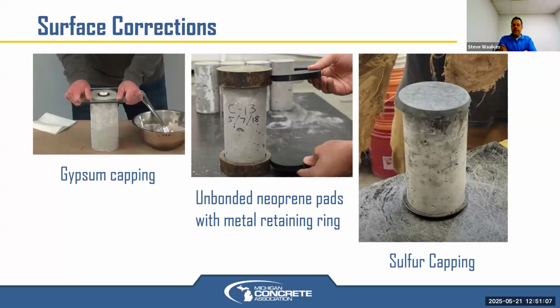Yes. That comes down to proper care and protection of the actual work, not just the test specimens. And that obviously is on the contractor to protect their work. MDOT specifications have information on what you need to do based on what you're placing: bridge decks, pavements, curb, whatever. So, below freezing, do this. And we have a guide on that as well.